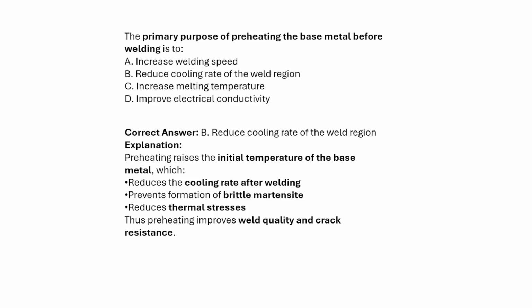Preheat treatment raises the initial temperature of the base material, which reduces the cooling rate after welding, prevents the formation of the brittle martensitic phase, and reduces the thermal stresses. Thus, preheat treatment improves the weld quality and crack resistance.